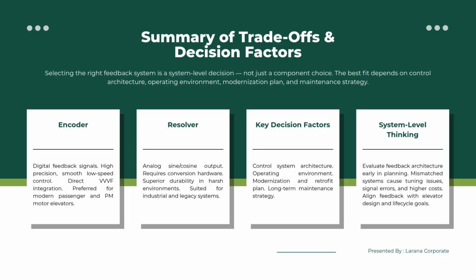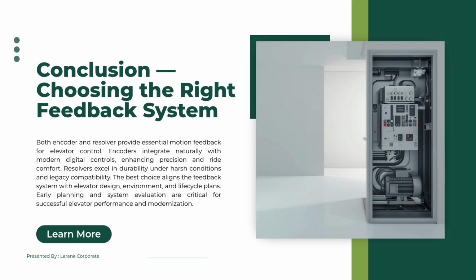Modernization and retrofit challenges. Modernization is where the difference between encoder and resolver systems often becomes very practical. Older elevators may use resolver-based legacy drives, outdated signal conversion hardware, incompatible controller protocols, or wiring that does not easily support a new feedback architecture.